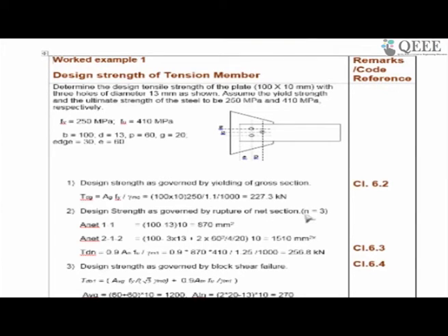If I take a zigzag, first let's take section 1-1, which is going through 1 bolt hole. So that gives me 870 mm². Then 2-1-2 is possible. This is 2-1-2. This is a zigzag section. So that is a possible cross section.